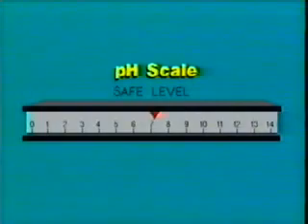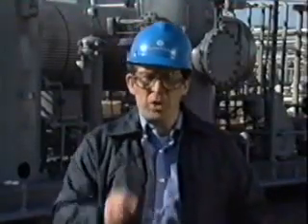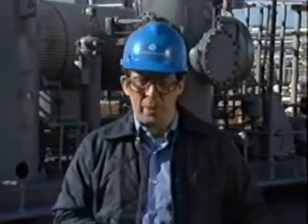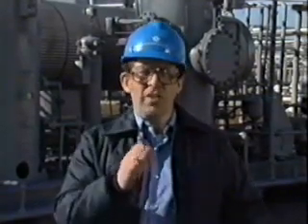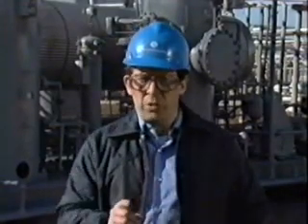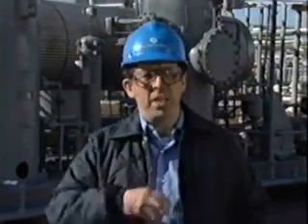A pH of about 7.3 is considered a safe operating level. As glycol pH decreases, the equipment corrosion rate increases rapidly, and troublesome corrosive compounds result. Raising the pH above 8 to 8.5 is not desirable because a more alkaline glycol solution tends to foam and emulsify easily.